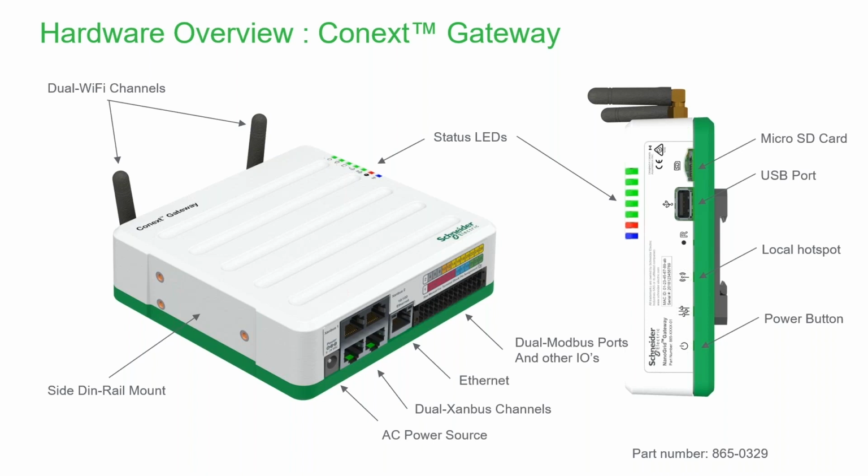You can still see them all together, right? So although you may have a number of inverters on one side of the channel and a number of charge controllers on the other side, you will still be able to monitor them together and see them together. You see an AC power supply connection here on the gateway. However, for the most part, the gateway will get its power from the SAN bus network. So this power supply will not be used for most systems.